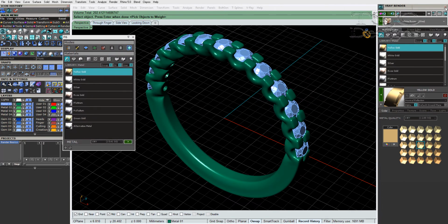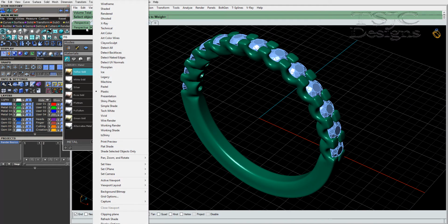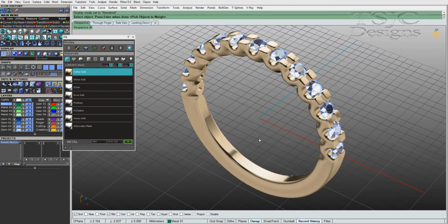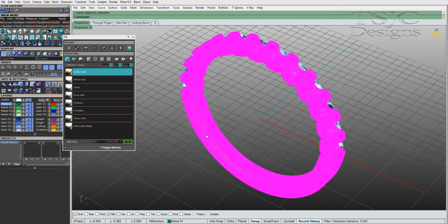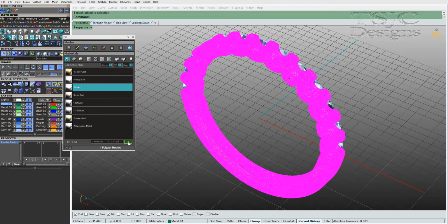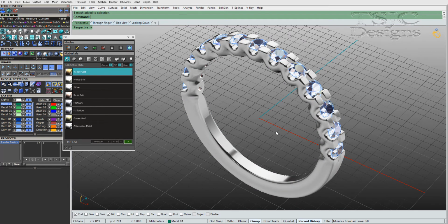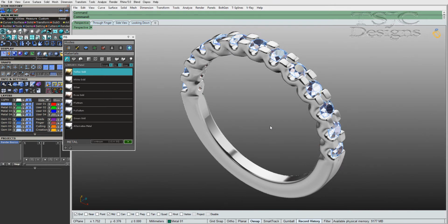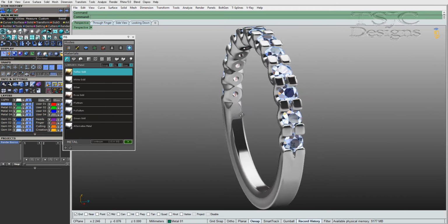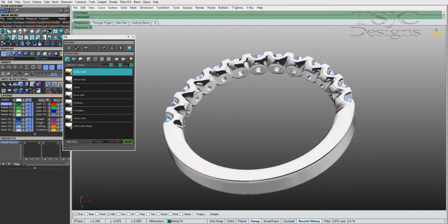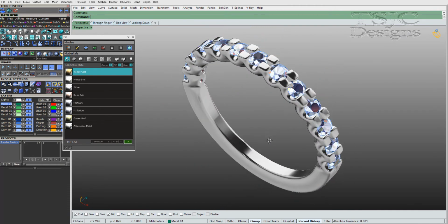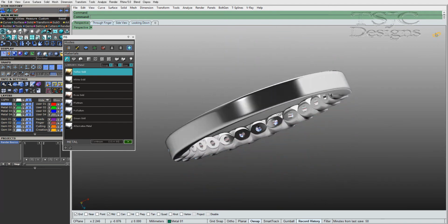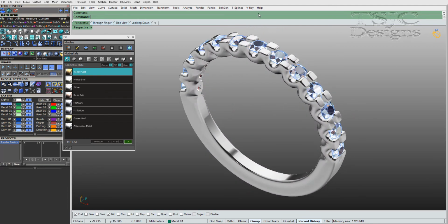This is if you don't want to open up the render engine. So if I go to rendered view, because I applied that material, so if I click that and click silver and apply it in this view, it will appear like that. If you press F7 on your keyboard, it'll get rid of the grid. So sometimes you could get away with just showing the customer this, and this is a kind of counter sketch view. I'm not sure whether Matrix Gold does this, it probably does.